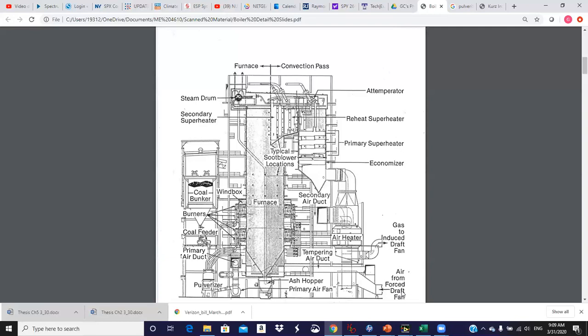Okay, over on the left-hand side, we see the coal bunker. So, you know, we have the coal pile outside. The coal comes in on rail cars. It goes through a crusher, which crushes it to basically 1 to 2 inch chunks or smaller. It's then transported via conveyor up to the top of the boiler house, and then the various coal bunkers.